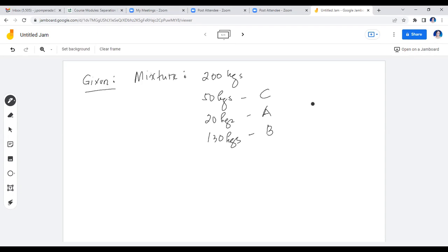Okay, now that's it. It's placed in a mixer settler and then the two layers, the extract and the raffinate layers, are allowed to separate. So your mixer settler could be one mixer there, and I'll show the equipment later. From in here, you will have a settling chamber, wherein at the bottom part you'll have the raffinate, and the upper part you'll have the extract. In some equipment, this settling zone is part of the mixer already; in some equipment, it's separated. So I just place it in here so it will be clear to you. From being mixed in here, the mixture is allowed to come to equilibrium and the two layers to form separately. Then your extract is always on top and your raffinate is at the bottom.